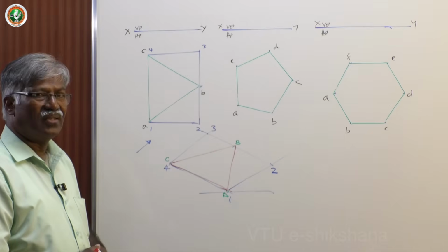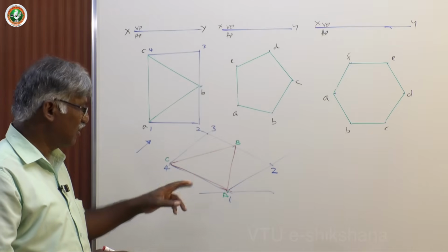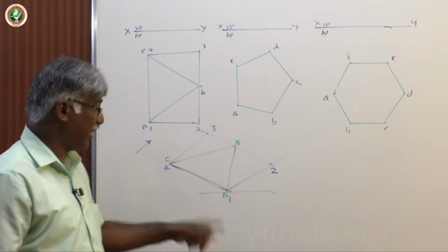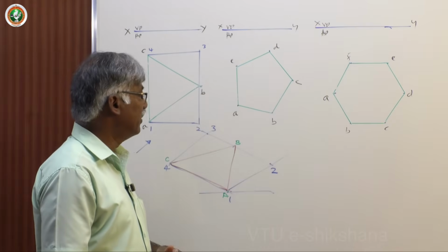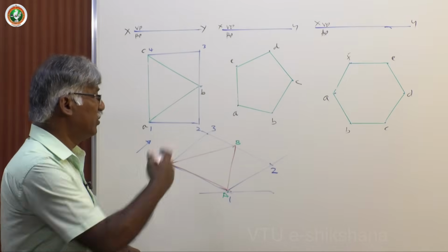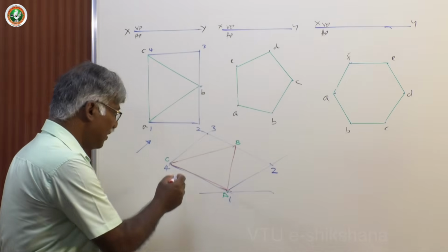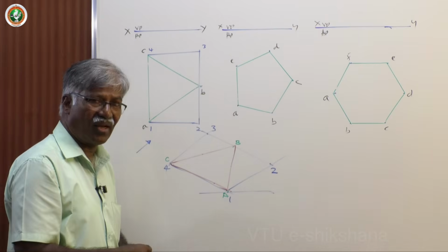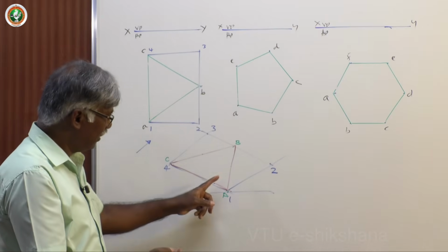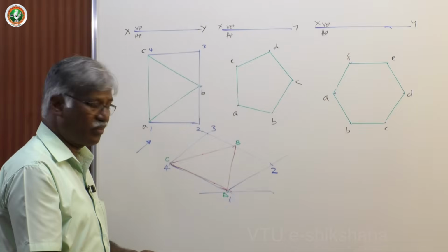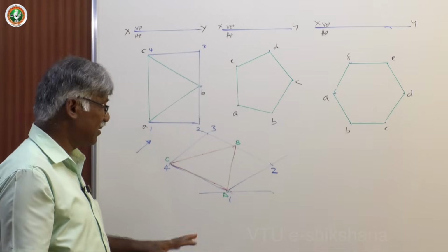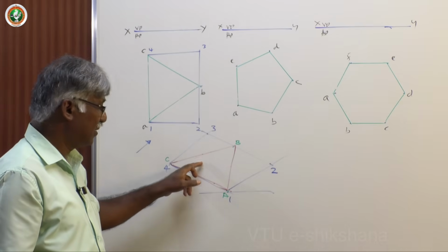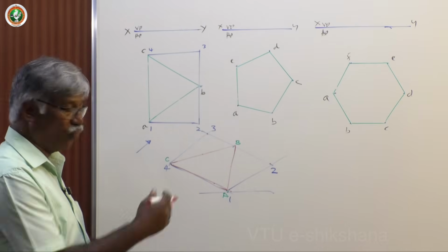That's all. You have to reduce the distance. So this is nothing but the isometric projection of a rectangle, triangle. Now how to draw this? And before going to the next figure, this is called an isometric line. These two are referred to as non-isometric lines. You can ask me one thing: why are these two the same here in the orthographic projection, but different here? That is the characteristic feature of the isometric projection. Here this is smaller, this is bigger. That depends on the view.